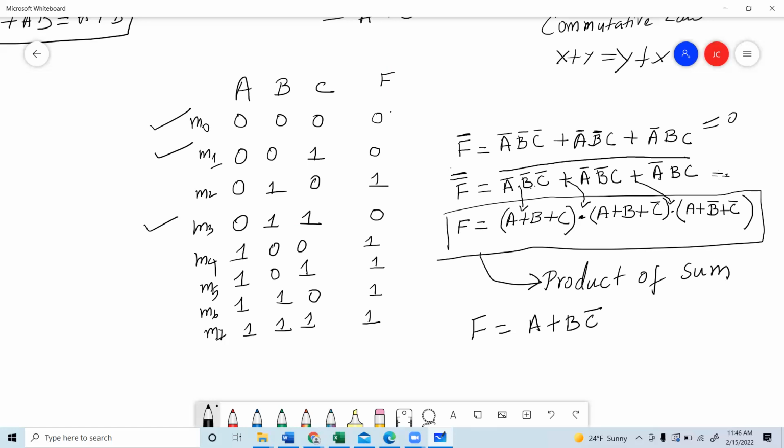Is that clear? So this is equivalent to this. They are basically the same, but again you have to use Boolean algebra to reduce the circuit. Is that clear? And for product of sum, again you can use Boolean identities to get the final value, which is A plus BC bar. I will leave that as something you can prove once from home. Are you getting my point?